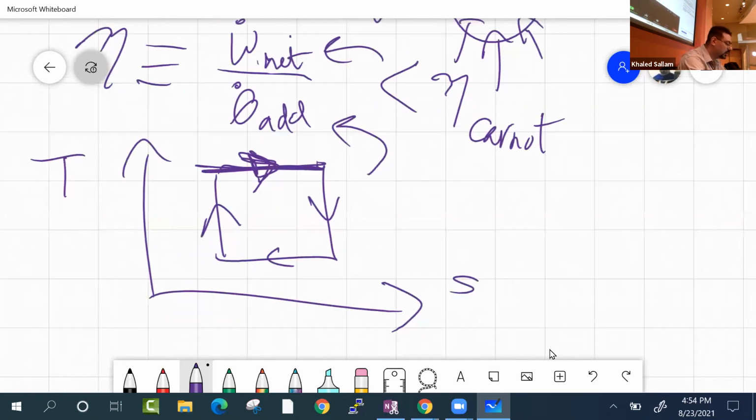And then this part, what is that? Isentropic expansion. You need a turbine that takes you from this to this isentropically, a turbine that has no friction. The steam will go into the turbine plates without sliding on the wall, without any friction. Is that possible? No, it's not. So the actual one will have to go to the right or to the left. The expansion will have to go to the right because the entropy will need to increase. If you give me friction, the entropy will increase.